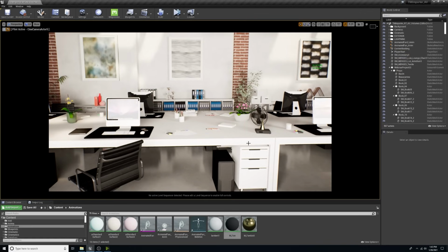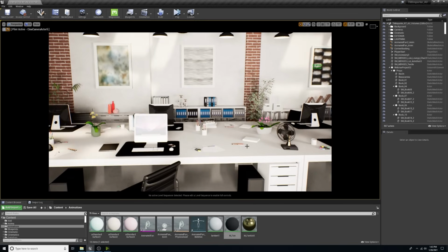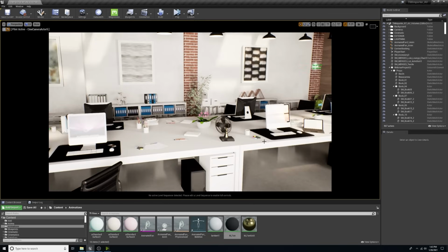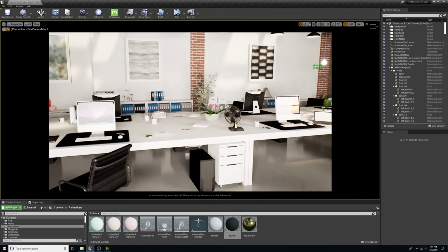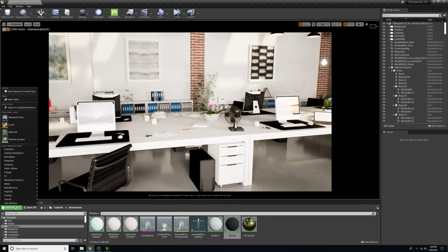Now you can bring in other animated features, such as any Anima files you might have. If you're not familiar with Anima, it is a 3D software that allows architects to bring in crowds and walking paths with characters. So I would encourage you to go to the AXYZ website to make sure that you have the most recent plugin for Unreal. And once you have everything downloaded, then you can bring in the Anima files by going through the same process we went through, the Add Import, and then importing the Anima file here.